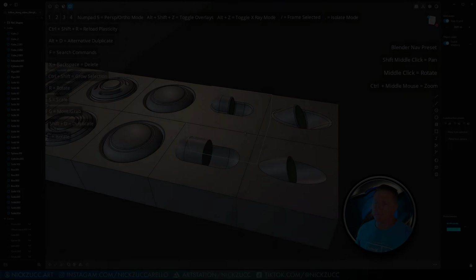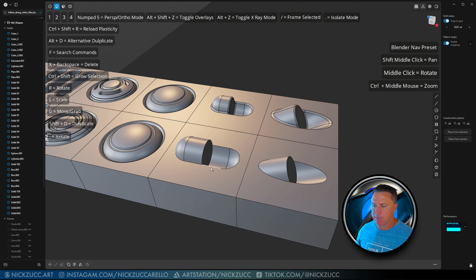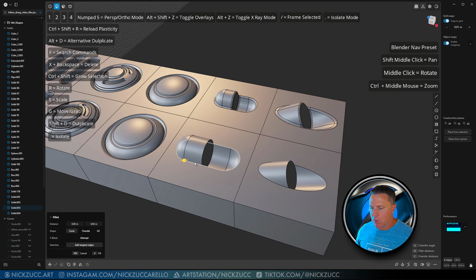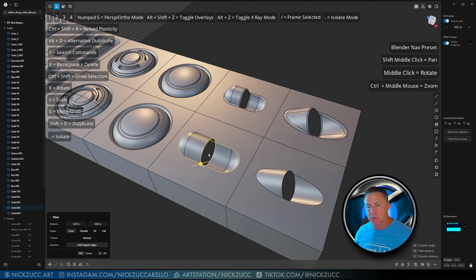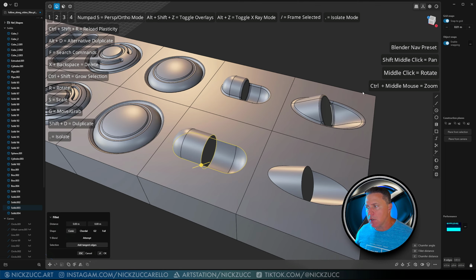All right, let's go ahead and grab the edges on here, tap 2, and we'll work our way around the entire thing. I'm just going to grab all of them by holding down Alt and Shift together, and I'm going to turn off all the snapping and then just try to drag this out and see what we get. So on this shape, it actually seems to work pretty good, at least for the fillet. If I try to do a chamfer, it's always failing on us.